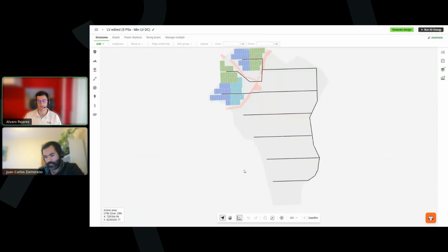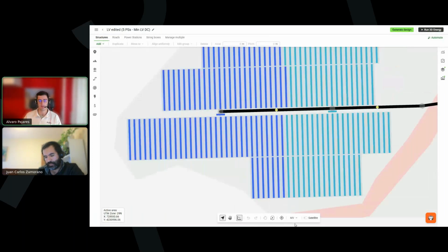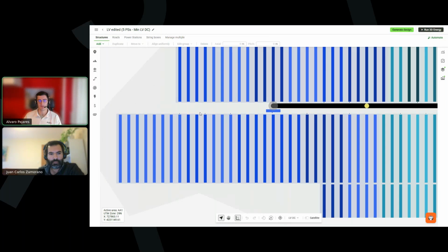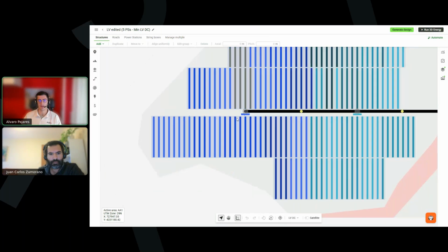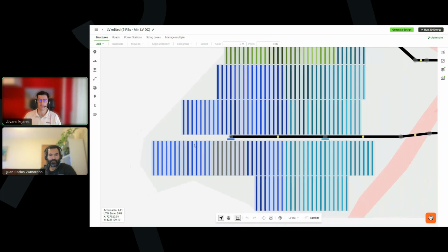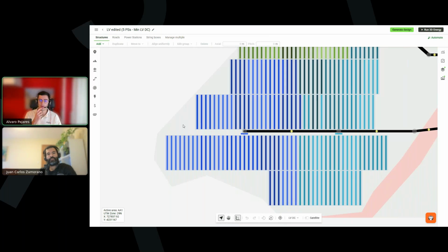where I took the boxes. We can see them here. We can see how all boxes are placed close to the road, and we have defined the low voltage groups according to that. We could evaluate these different configurations, get the results with our financial analysis, listing of cables, bill of quantities, and so on, and see what configuration is better for our case. And we can do that, as I mentioned, also for the energy calculation.